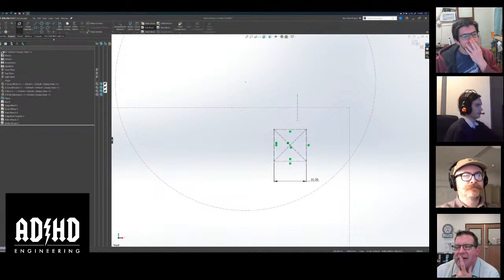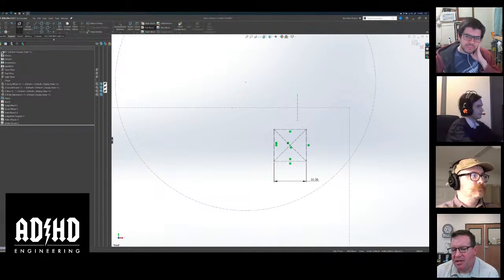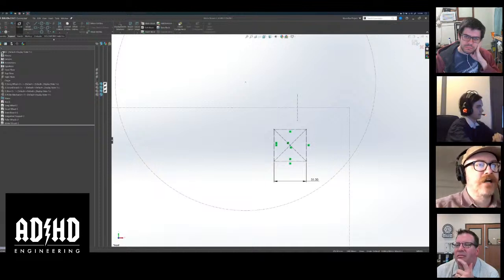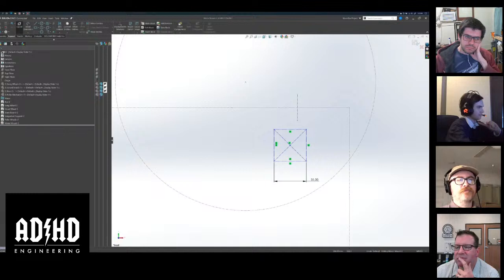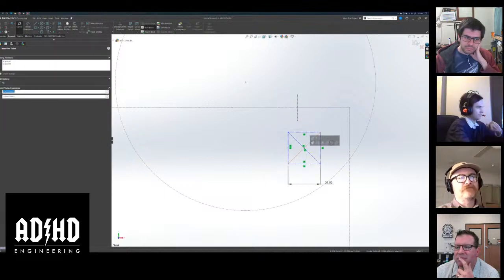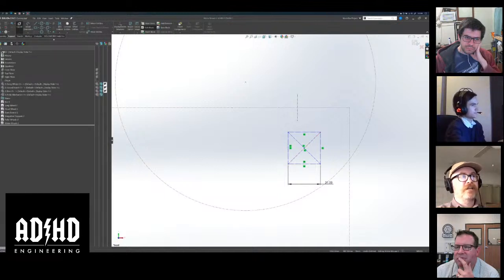All right. So now show us, David, how you set the location of this block that you've made, which is our motor mounting position, relative to the other sketch. Okay. So first we have to leave the block. For now, I'm going to delete that. We can come back to that, but normally I would not expect this to be fully defined. To leave the block from editing, we just click Edit Block again.